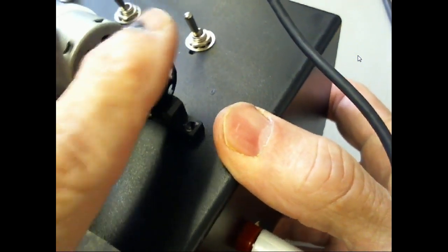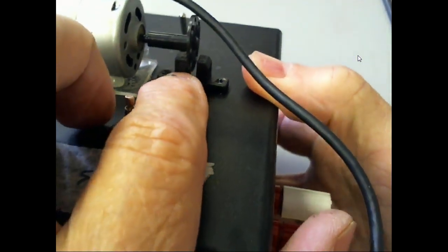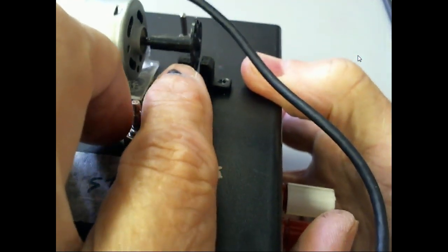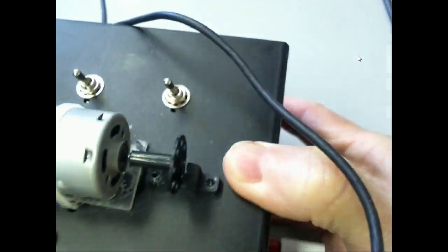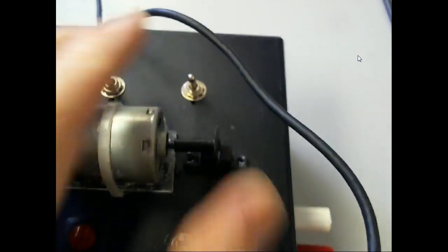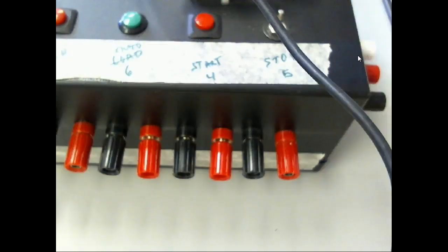An encoder is a device. You can see when the motor spins, it spins these little holes. This is what we call a through-beam sensor. So it shoots a light beam across, and every time this thing turns, when the hole goes through, it lets the light go through, and then it blocks it. We can use that to sense speed. So right now all we're going to do is use these guys over here.